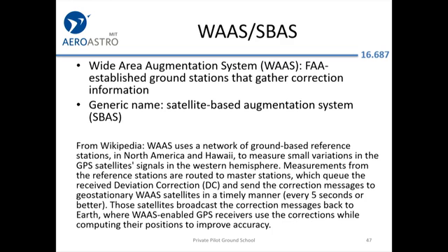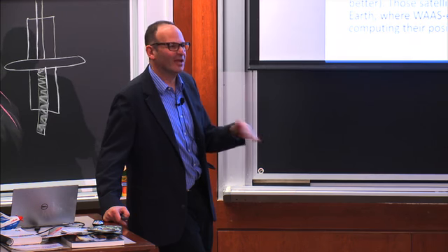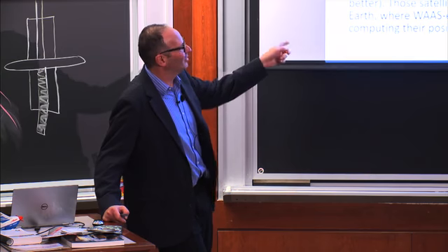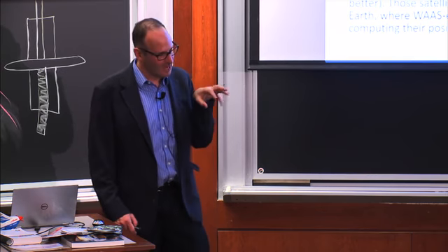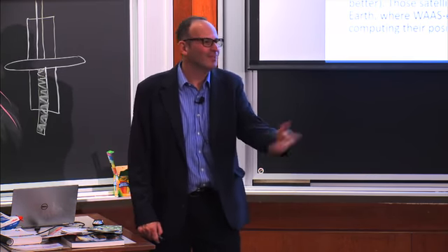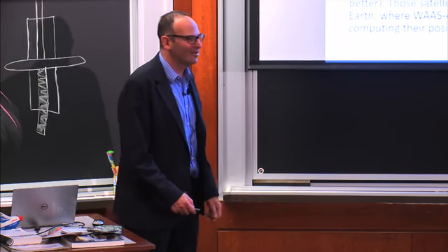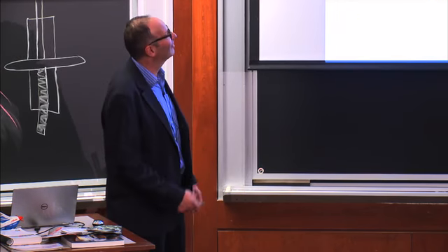You can get accurate enough to actually fly right down towards a runway. So the GPS system, which launched in the mid-90s, enabled the moving map, and you were never lost again. You always knew where you were. But the WAAS system is what enables these GPS approaches where you navigate in 3D, to within 10 feet or something of precision right down to the runway.